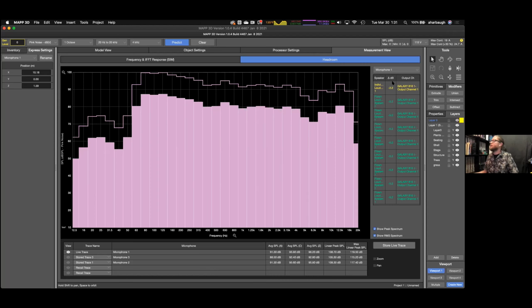So the thing to note about this delta decibel table is when we measured the input sensitivity of the loudspeakers, the way we've scaled our product line leaves some headroom left over to push it past 0 dB on the input to that loudspeaker and still get some linear headroom out of a lot of our products.